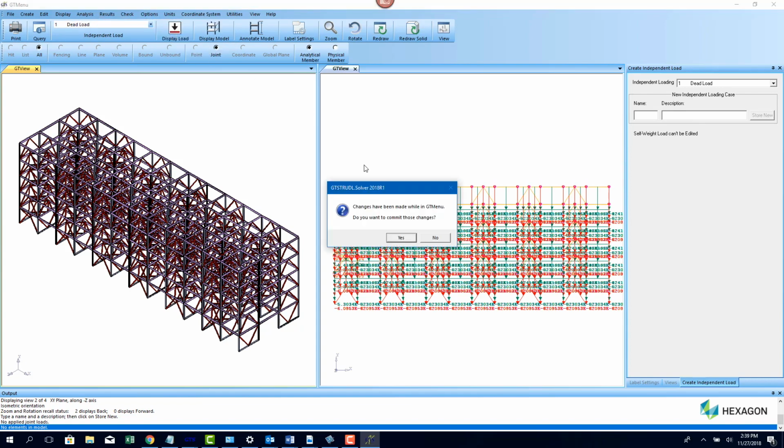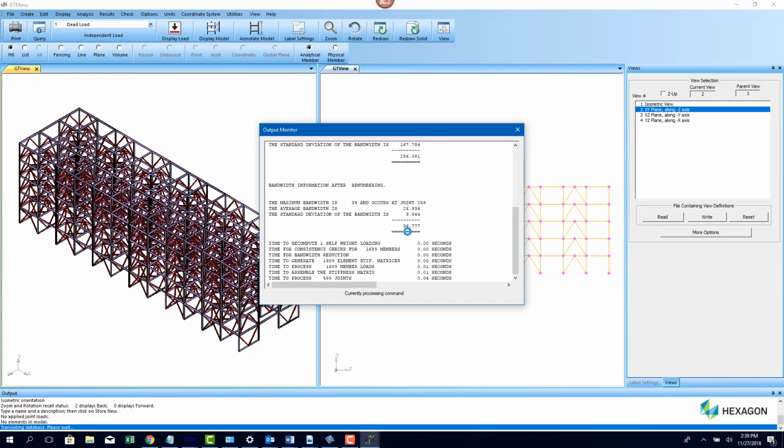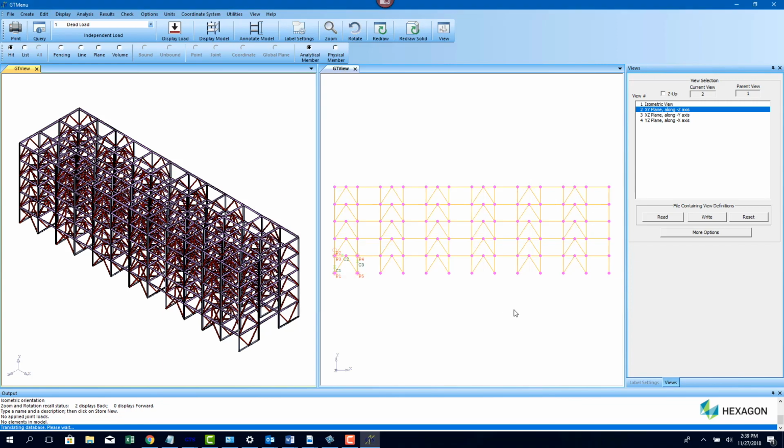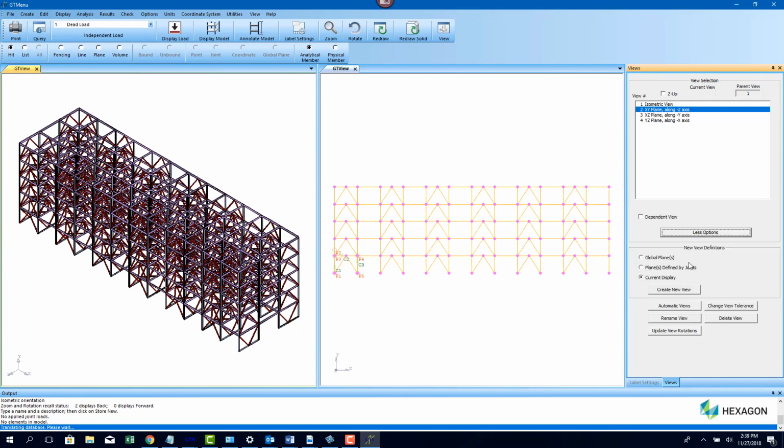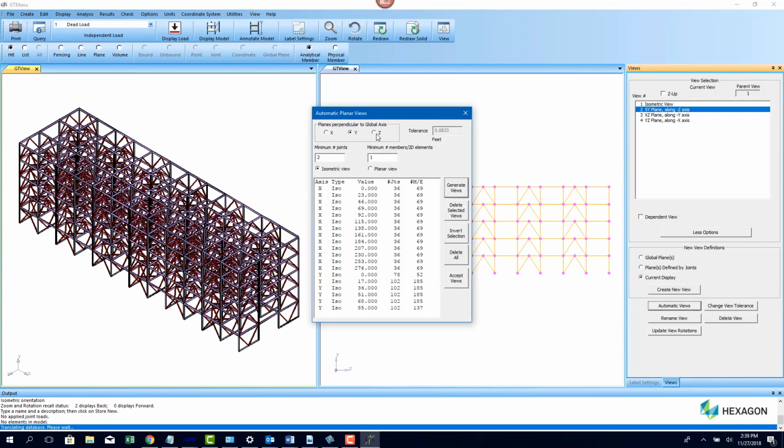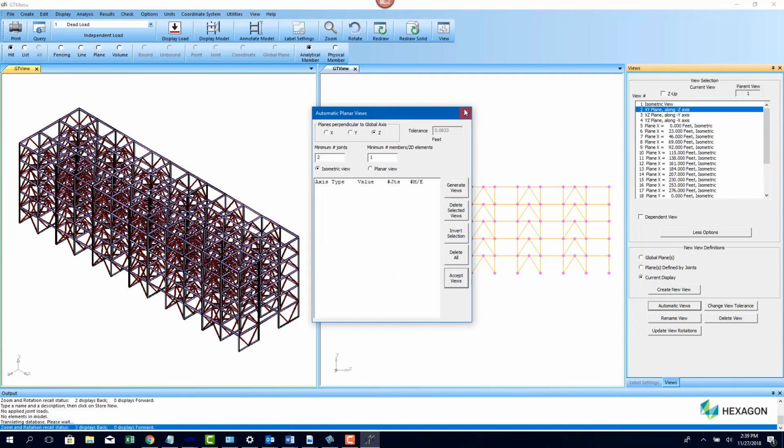Some of the members need to be activated and deactivated depending on the load condition. By that I mean that this structure needs to be designed for in-place, barge, and lifting conditions and varying support conditions. The governing load condition will vary for each member.